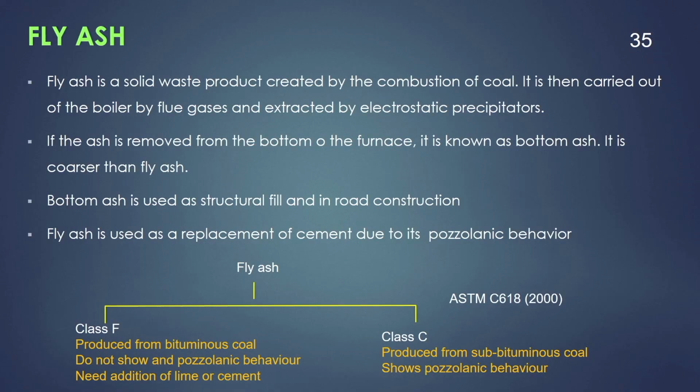Next comes the fly ash. Fly ash is another product which can be used along with other materials. Generally, fly ash is not used alone for soil improvement. Fly ash is generally used along with the lime or cement.